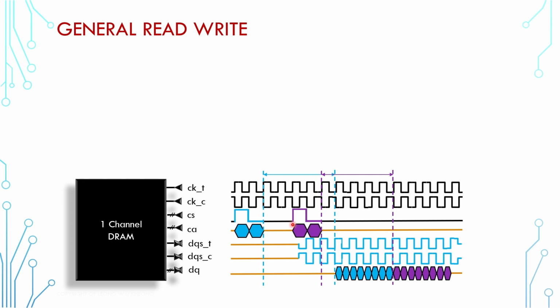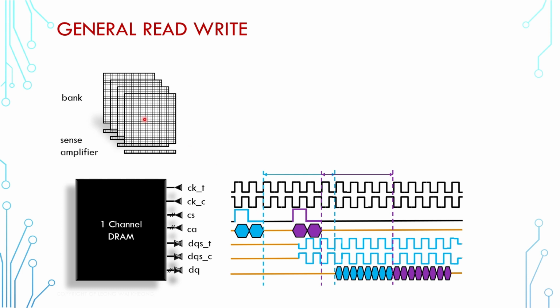Now, what's even more interesting, different kinds of command have different delay. As a simple example, if the next command is writing to a different row, the delay is different as compared to if the next command is writing to the same row, because the row is already activated. At the end of the day, the controller needs to know the timing very well. The time when to send the next command, and sometimes the type of the next command, depends on what the current command is. And this is on top of the requirement where we need to constantly send refresh commands to idling data on other rows.